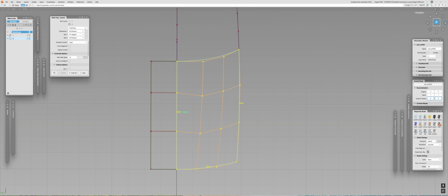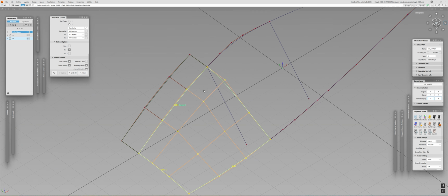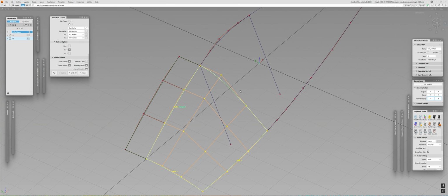The only thing missing is the collinearity, but we can easily tweak it by using the specific checkbox. Now that's great, but I actually want to show you a different method of doing so. When you have this technical surface, you need to create the curve, you need to create the surface. The surface is always supposed to be in front of you, so you need to align it. If you delete the history for your rail, the alignment just goes away, so you need to redo it again, and so on and so forth.